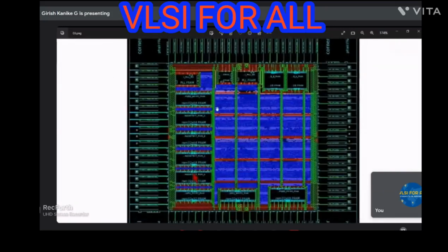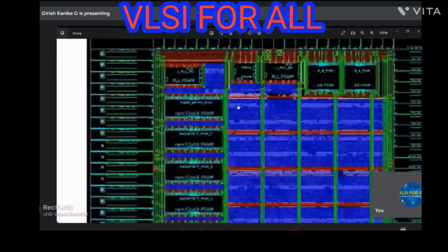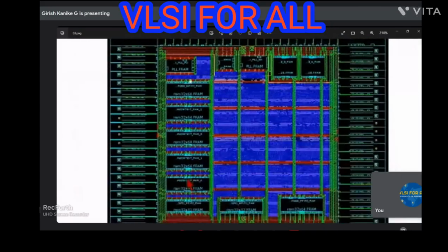In floor plan, you will be given certain memories, certain ALU logic, and so on. Those will be blocks that you need to place inside the block. Consider this thing as a block. I haven't shown a block picture. So if this is a block, I have to place the macros inside the block, and standard cells inside the block. The first thing you place is macros.